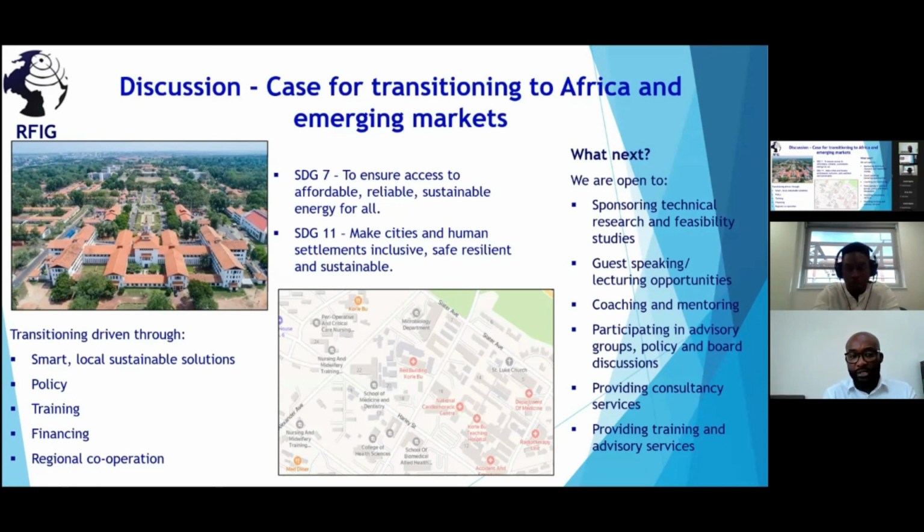So off we went and designed a system using locally manufactured solar water heaters, and we connected them via network to the ablution blocks for the accommodation blocks we'd designed. And we also harnessed the heat from comfort cooling to provide a backup heating system for times where there may not be enough coverage for the solar collectors.